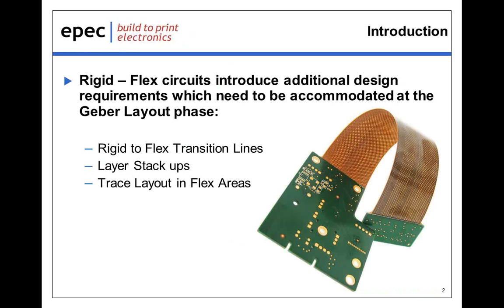So a couple of the more specific and more important elements that a rigid flex design introduces into the layout phase revolve around the presence of rigid to flex transition lines. There are also some elements related to the layer stack-ups and also a couple of items that pertain specifically to the trace layout within the flexible areas of the design.